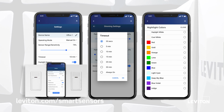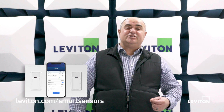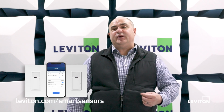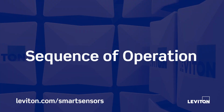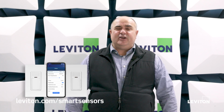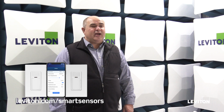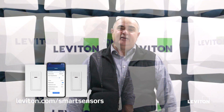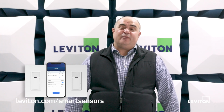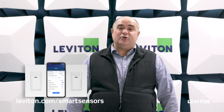With regards to code compliance, one of the things that we've seen a lot of the specifiers as well as the contractors that are really doing it right, they have developed what's called a sequence of operation for all of the various room types. And the biggest benefit of that sequence of operation is it sets standards that are in fact code compliant on how each of the different spaces are to operate. Well, once you have that information, it actually allows setup of the control system to go very smoothly.